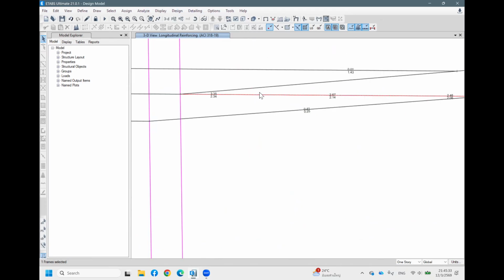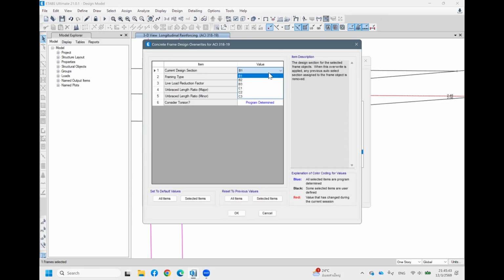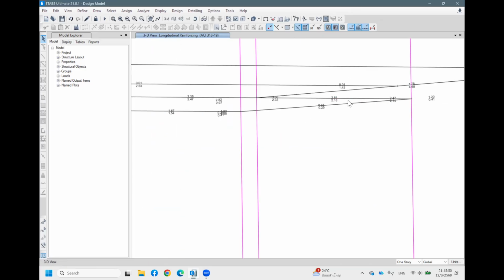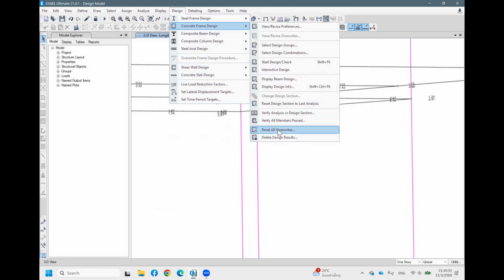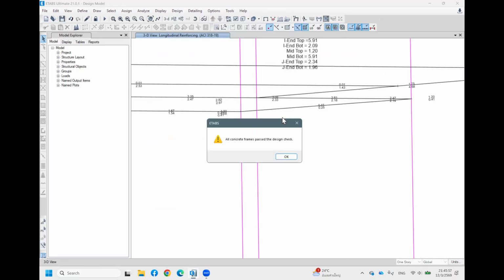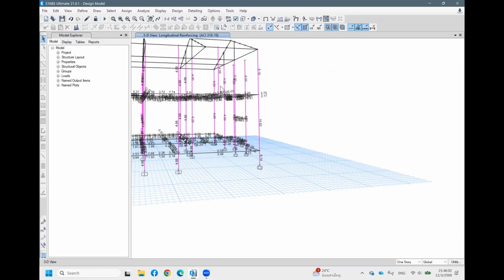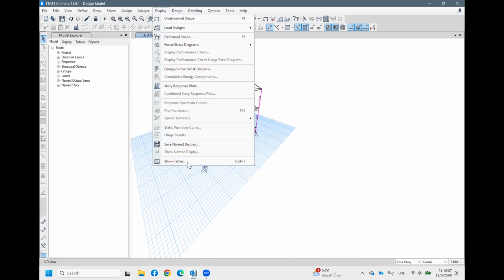So just right click and then here it shows overstress for shear. So we just do override and change this beam to be B2. Click OK. Okay, now it passed already. Now let's go to this side again. This side and then verify all pass. Okay, now this side passed. When this side passed, then let's go to table again.